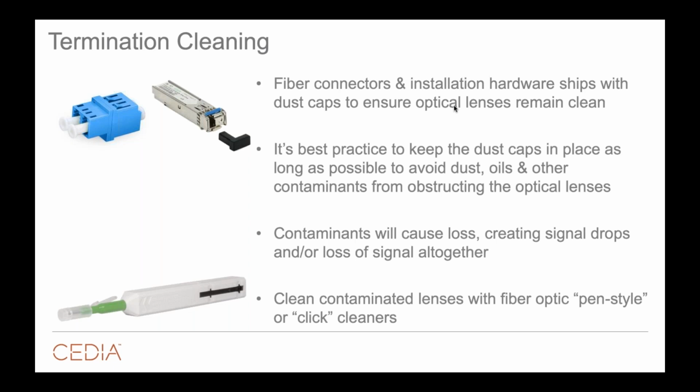I will tell you though, if you check your connectors and they're terminated properly, the vast majority of the time, loss comes from dirty installations. And this is where best practice really comes into play. Anything fiber optic is going to come with dust caps. Keep those dust caps in place as long as possible.